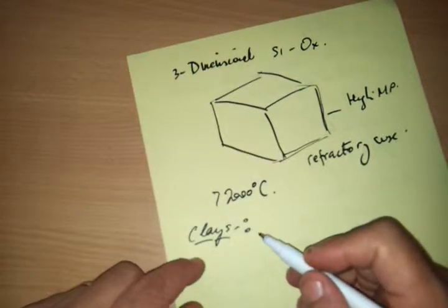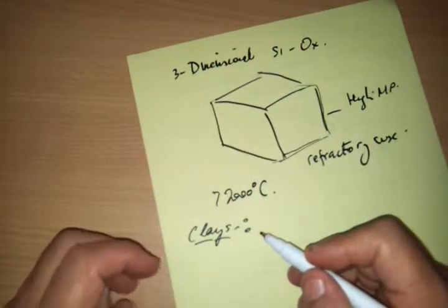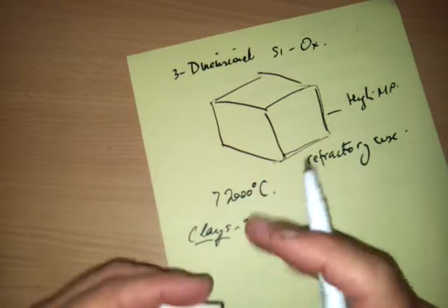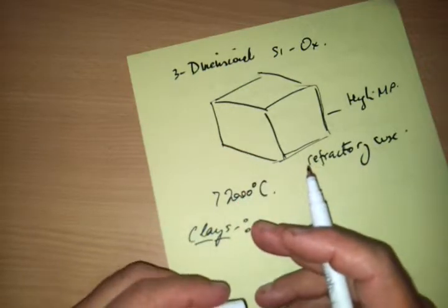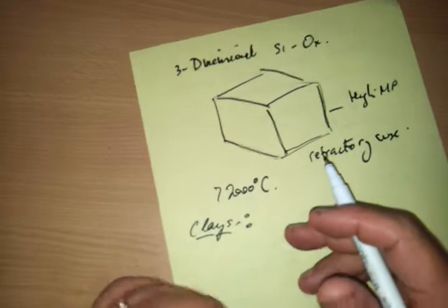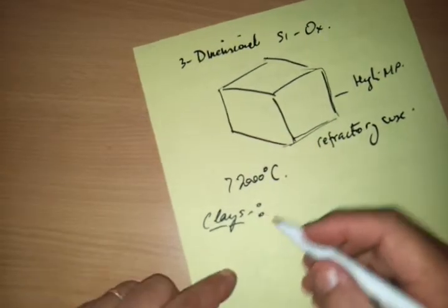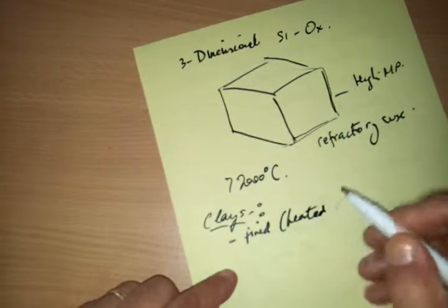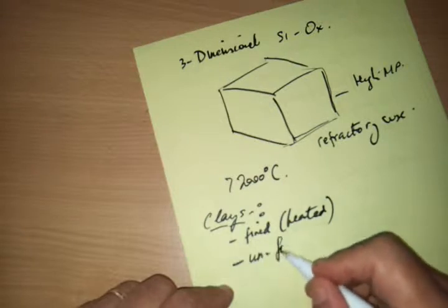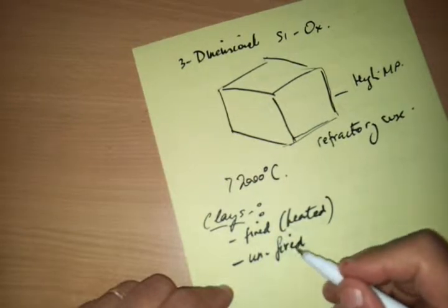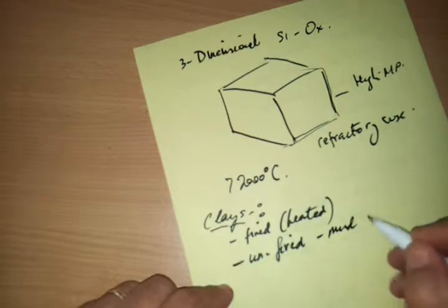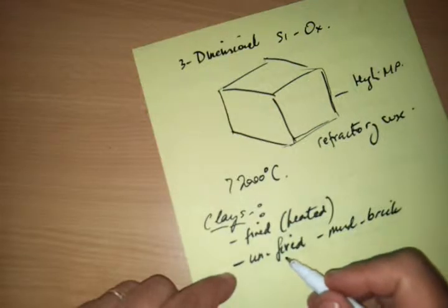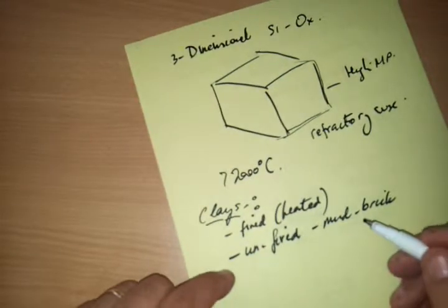Now, depending on the temperature which is applied to the clay, the water can be added and it can be softened again. The water will be reabsorbed and the clay can be reshaped and remolded. But if the temperatures reach a certain degree, permanent changes take place in the clays, and that's called firing. So clays can be fired, which means to be heated, or unfired, so just naturally dried. Sun-dried mud brick, for example, is an example of an unfired clay brick used in civil structures, especially in ancient times when high temperatures were expensive and hard to achieve.